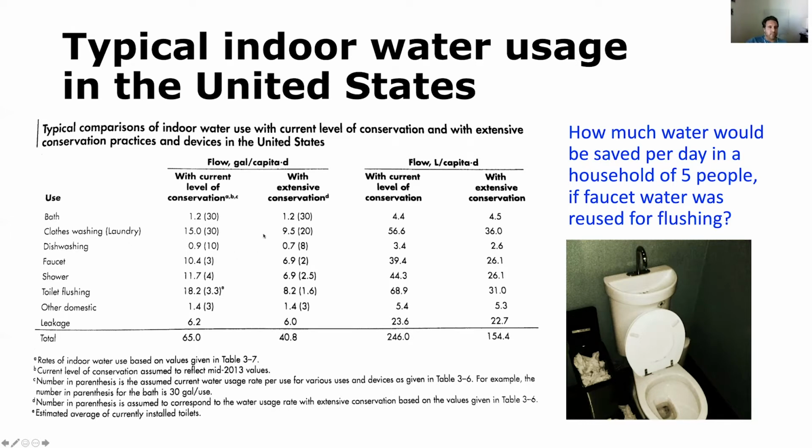of these decrease. So uses such as bath, wastewater from the bath, that would tend not to change very much with conservation. However, clothes washing, laundry wastewater would tend to decrease quite a bit, given the technologies that are now being commonly implemented in washing machines. And the same goes true for toilet flushing. You've got low flow toilets as well. And some of these change more drastically than others when you talk about water conservation.